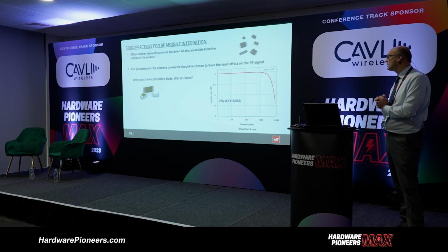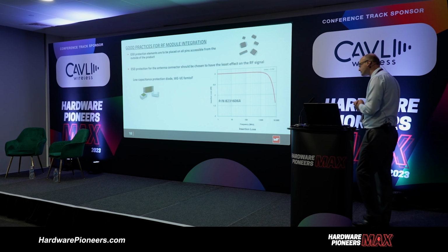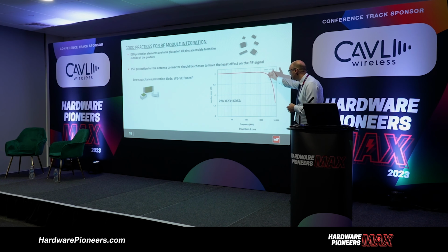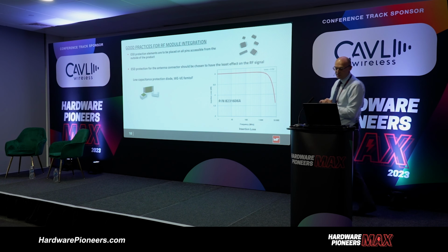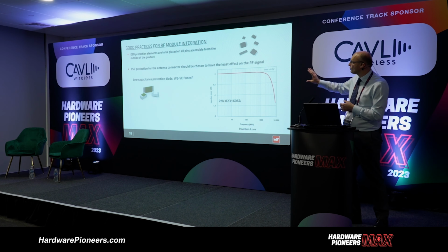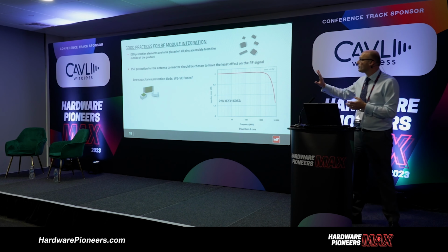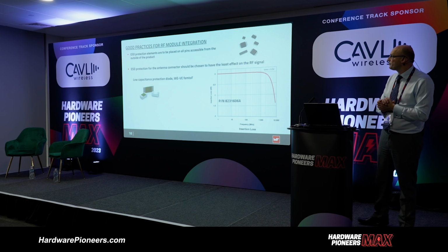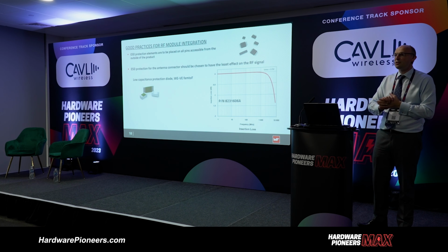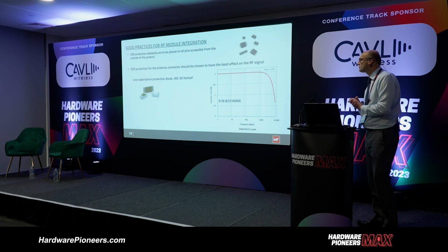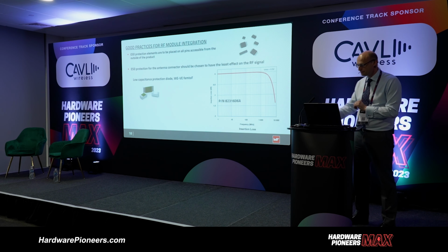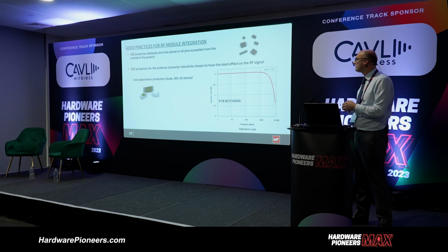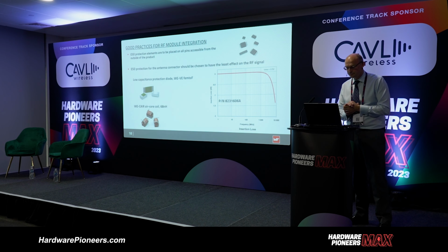Capacitance at high frequencies will lead to insertion loss, and that's what we're showing here as an example of a standard TVS diode. And so certain manufacturers, we being one of them, no pun intended on that one, have femtofarad capacitors with very low insertion loss up to around 8 gigahertz in frequency. So these can be used on your antenna port for protection.